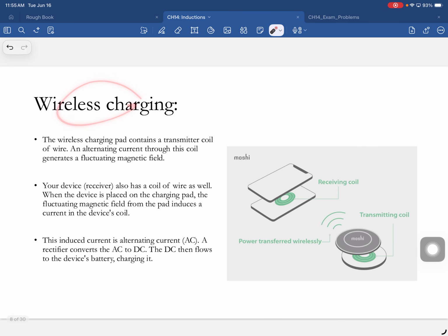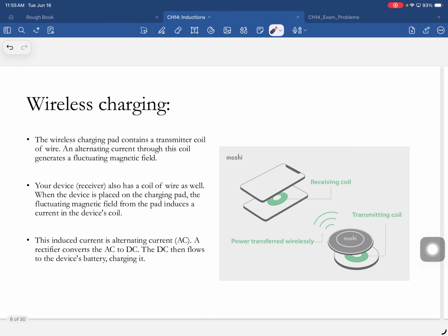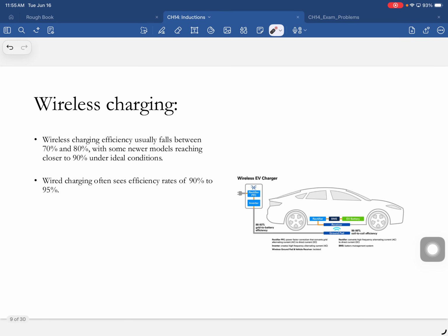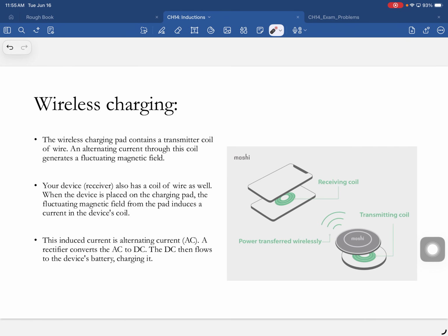So wireless charging also works that way. Here's the primary coil. Here's the receiving coil. And they put magnets on the cases, so the receiving coil is aligned with the primary coil. So here is the magnet on the case. And again, all this is possible because the receiving signal is an AC signal, and you have to convert that to DC before you can charge the battery.